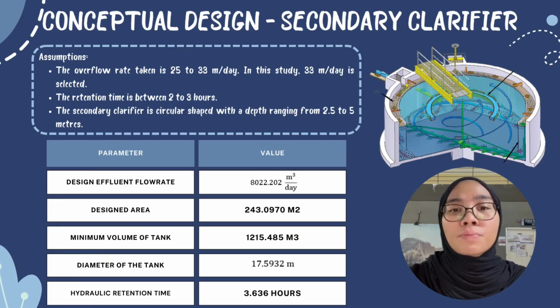The clarifier operates under steady state condition, maintaining a wastewater flow rate of 4,011.46 meter cube per day. It is designed to remove at least 95% of suspended solids, ensuring high treatment efficiency.